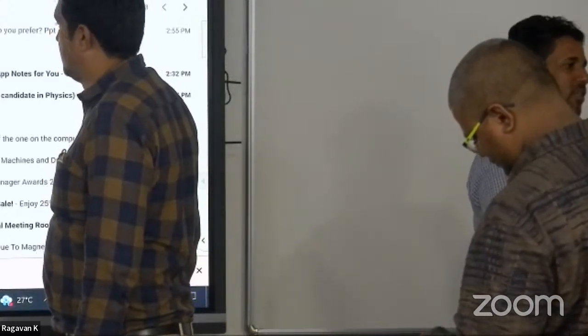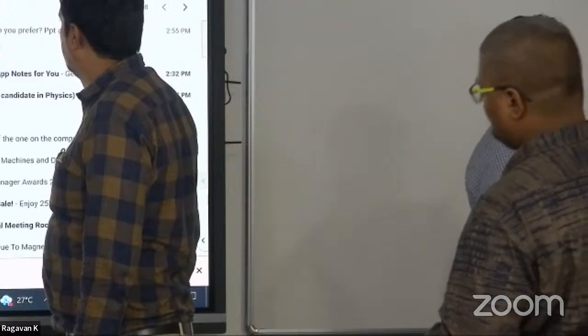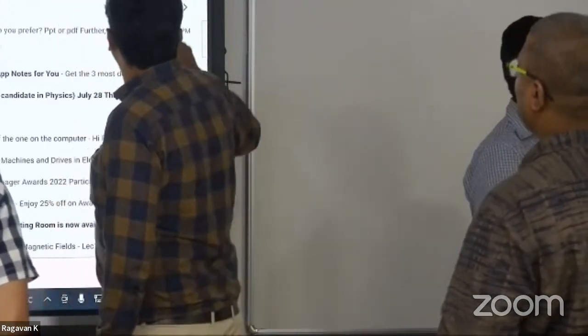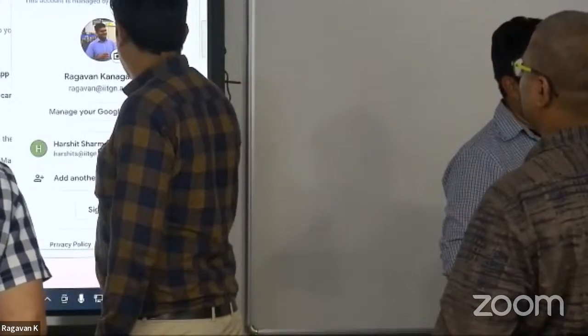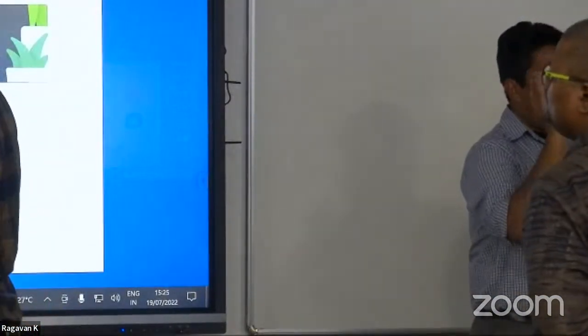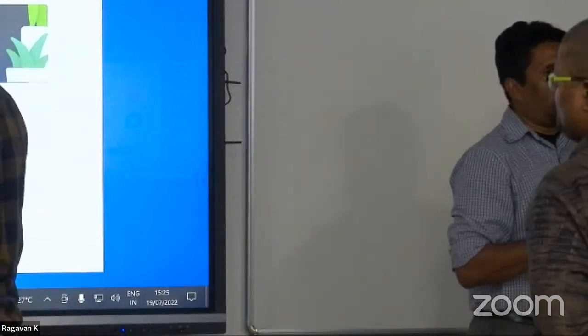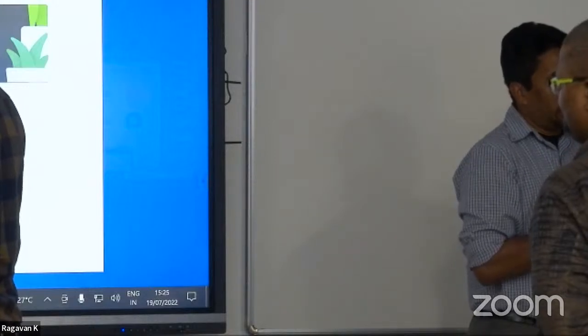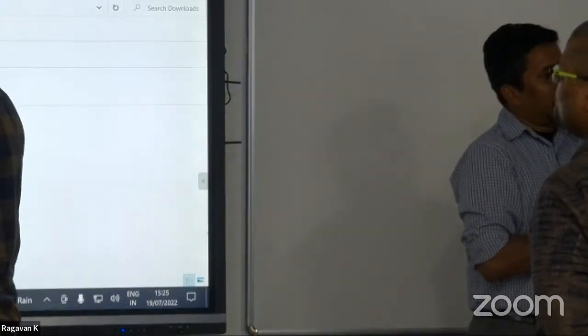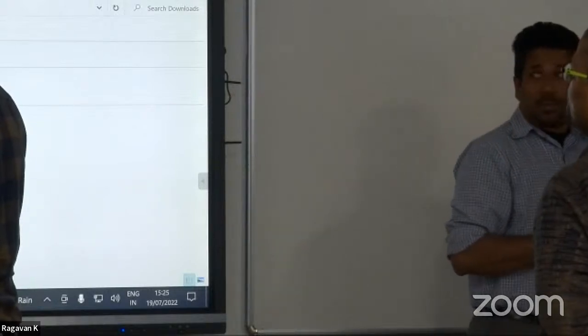The shape would be changed more than it was previously, but it should not be asymmetric. Asymmetry means, over the complete circumference, can there be a magnetic field distribution that doesn't repeat? It shouldn't. Once again, I don't know if there's a specific reason why you feel it must. Unless your design itself is asymmetrical, your field distribution should be consistent.